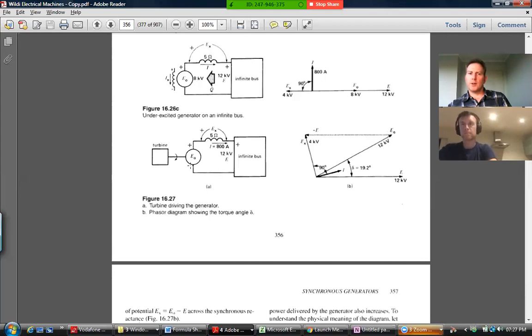Again, from a circuit analysis point of view, you've got a vector here from a minus to a plus. Kirchhoff's law around here, that would be like a rise. And if a rise was here, it would force current this way. That would be a vector with the positive end here and the negative end there. So the vector would be pointing to the left. So it would be a drop if we're going around like that. And then the infinite bus here, if we're feeding current into it over there, we're assuming that this is a more positive terminal than that one, and we're forcing it in, like charging a battery. You'd be forcing a current into the positive terminal to charge it up. If it was the other way around, it would be busy discharging.